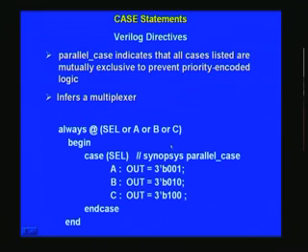So you have to tell once again that only these mutually exclusive cases are being considered here, and if you do not put this, once again it will infer a latch like the previous case. Notice that this full case and parallel case, it is not a must that you should adopt this. If you are not happy with it, you can refrain from using them and use the conventional method which has been already covered in the first, second or third lectures, right.